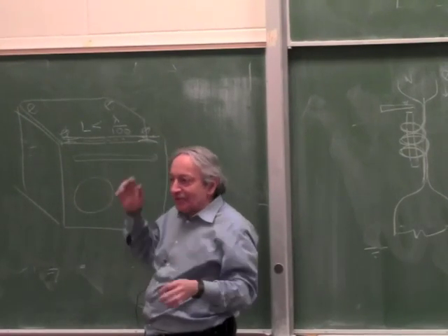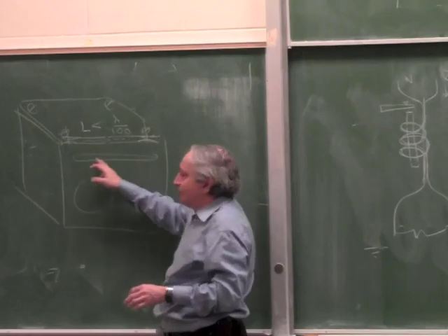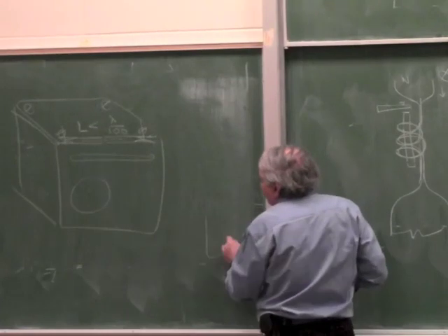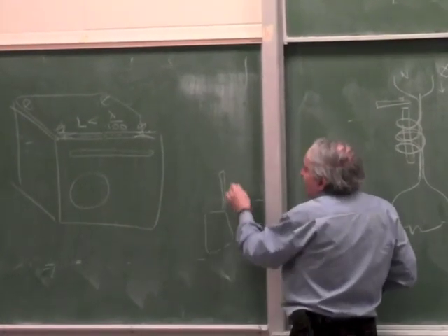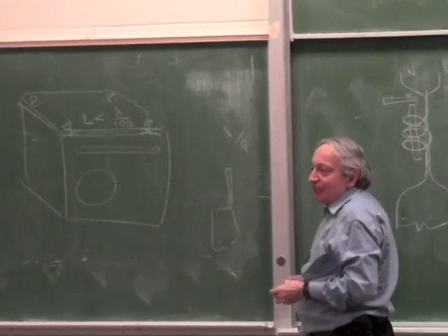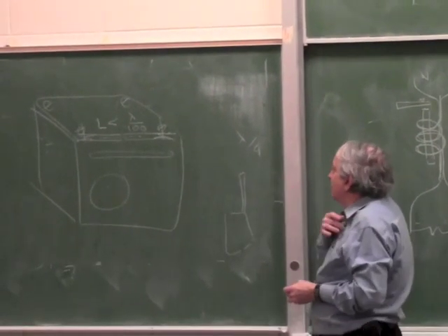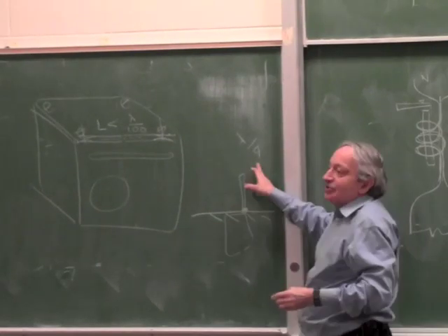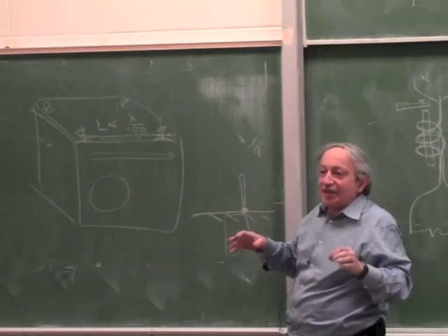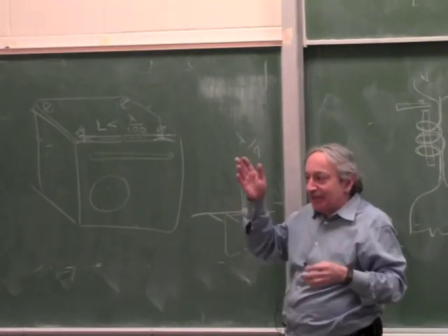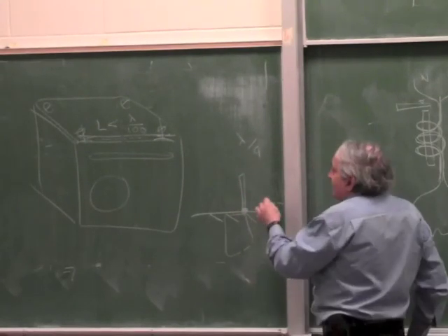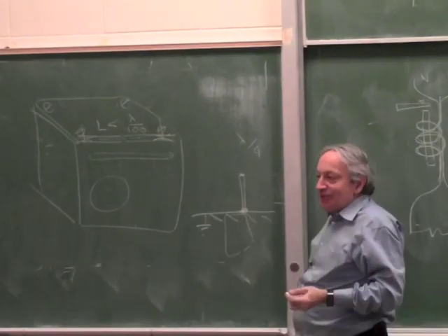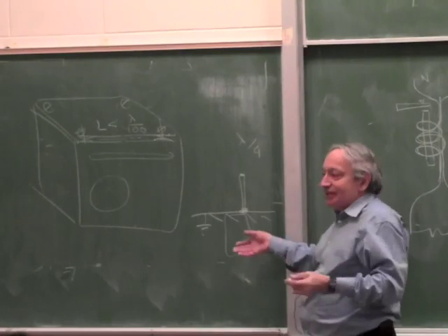Now again, I don't want to get into electromagnetic field theory right now, but there is such a thing as a slot antenna. Or even think of the dipole antenna. I mentioned in a cell phone, in the old days cell phone, which had an antenna. This was a lambda over 4, what's called a monopole lambda over 4 antenna. And the way it works, the bottom is grounded. Actually, the best example is your car radio. Look at the cars. Every car has a car radio and has an antenna. Or the old cars, you could see the antenna wire. Now this antenna is grounded at the bottom, but still has full potential at this end. Otherwise, it wouldn't pick up anything. Right? Because that's a standard lambda over 4 antenna.